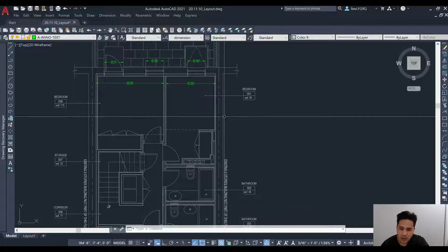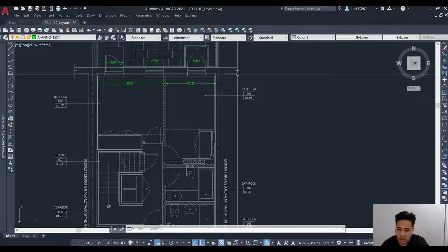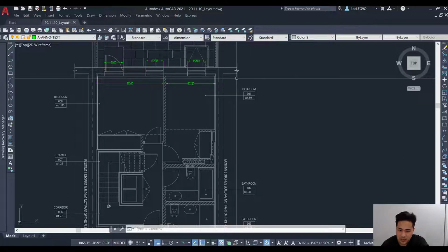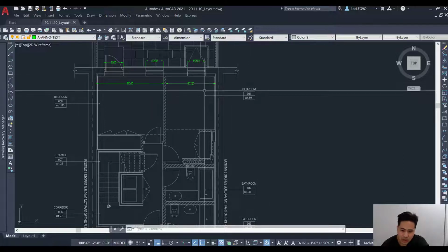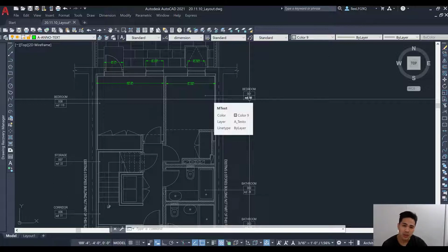In this example, the building is actually attached to an adjacent property on this side, on the right side as well as the left. But we're also going to consider that an exterior wall because the code in New York City sometimes requires a space between adjacent buildings just in case of an earthquake or some type of movement in the building.